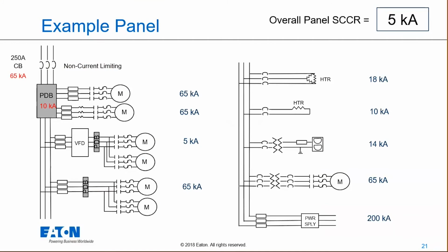So just to let you know, if you can design your systems to handle 65 kA, you're probably going to be able to do 75 to 80% of all applications out there with no problems. In most cases, like I said, at the secondary terminals of that transformer you'll see 65, but as you get down through the facility, 35 can be more common. So even in many cases, if you just design for 35 or 45, you can get to those ratings. It seems that most overcurrent protection devices, when we're talking about breakers and those kinds of devices, are all going to try to get to the 65 kA rating.